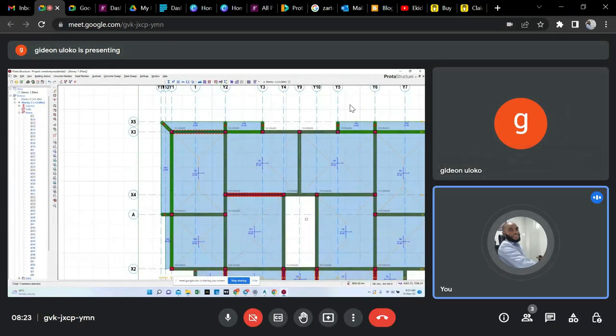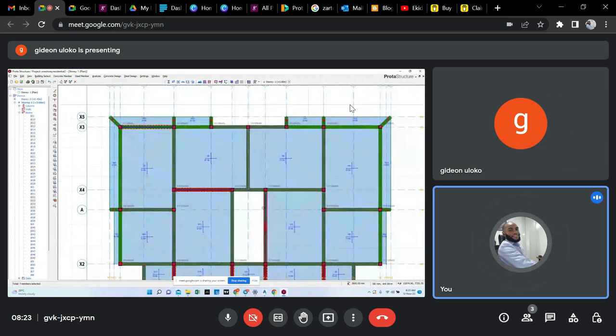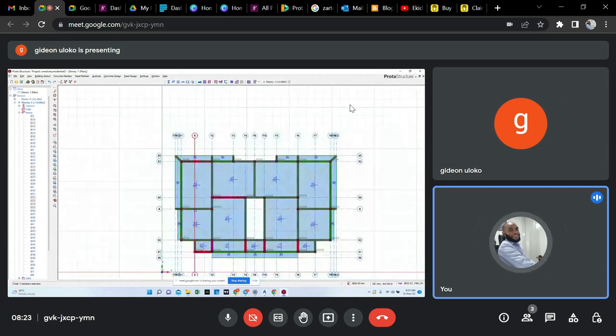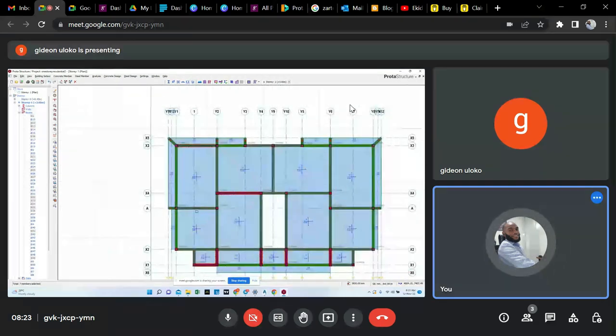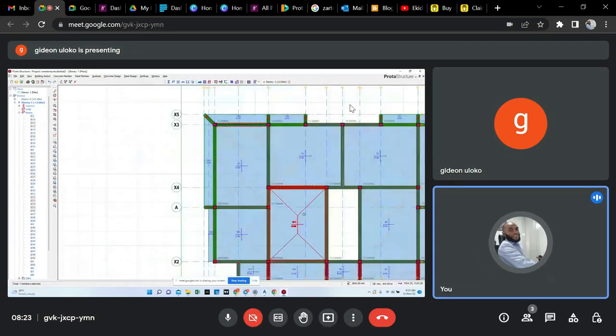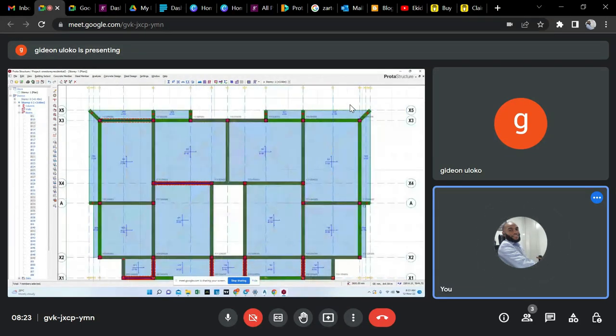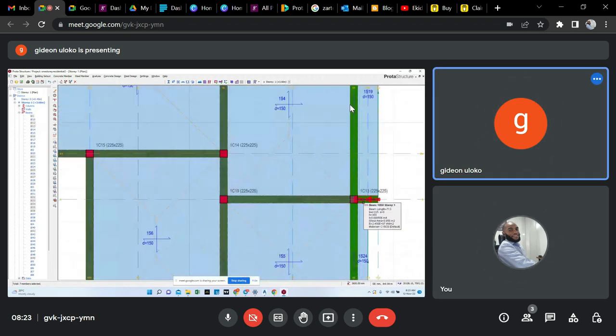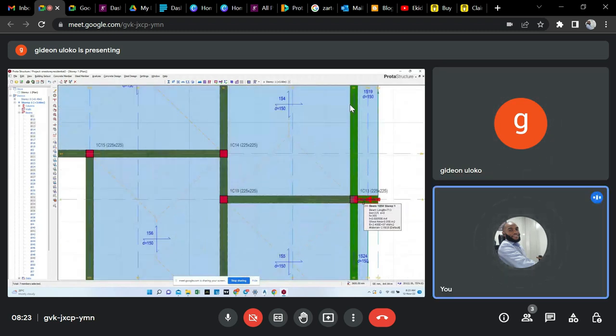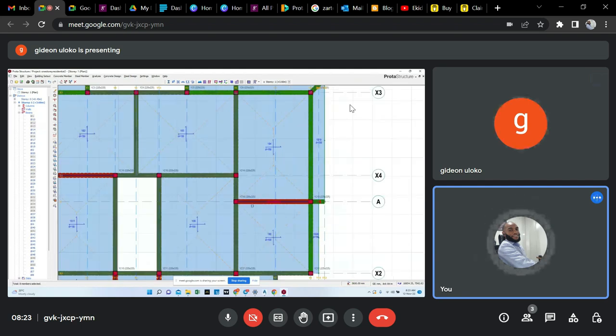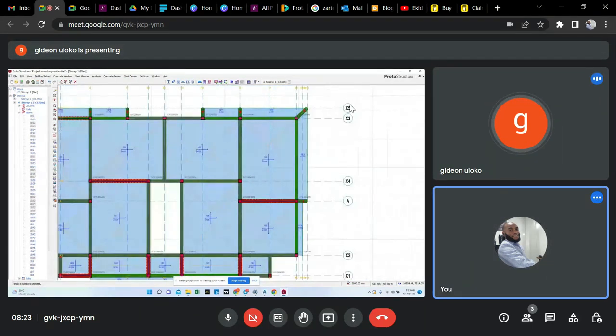And on grid line A, that cantilever end, which is the left end, should be hinged. No, this other beam, not that side. On the other side, yes, that one should be hinged. This one, not that one. The I end of it, which is column 19, that end should be hinged. Yes, that beam. So right now, right click and apply hinge at I end.